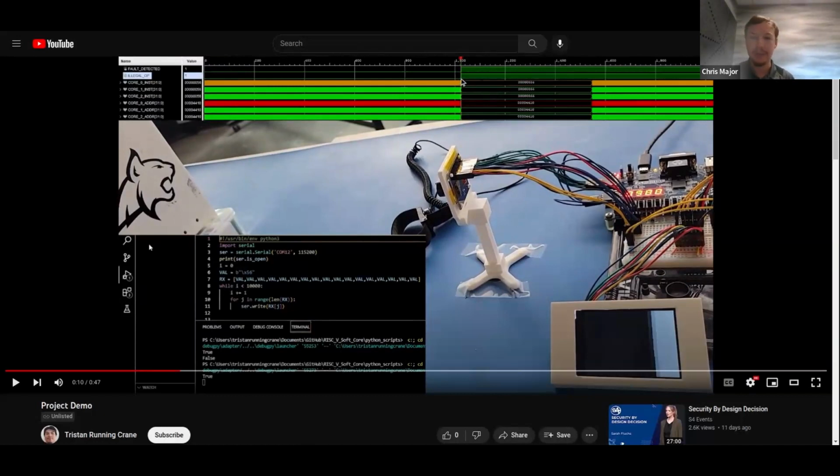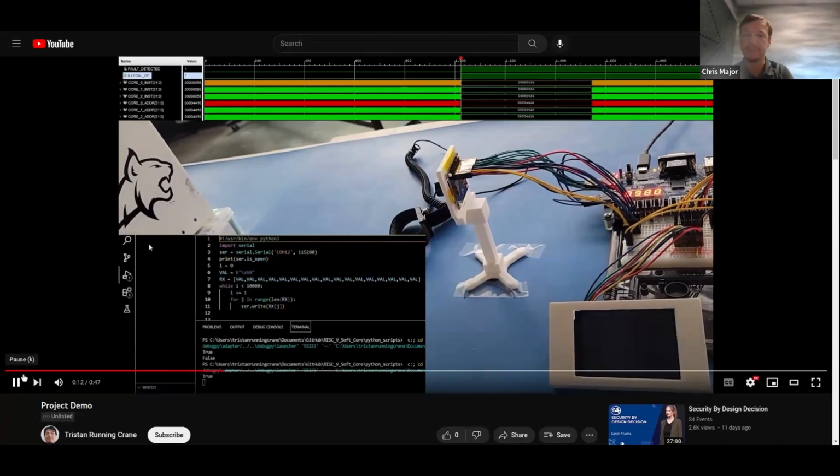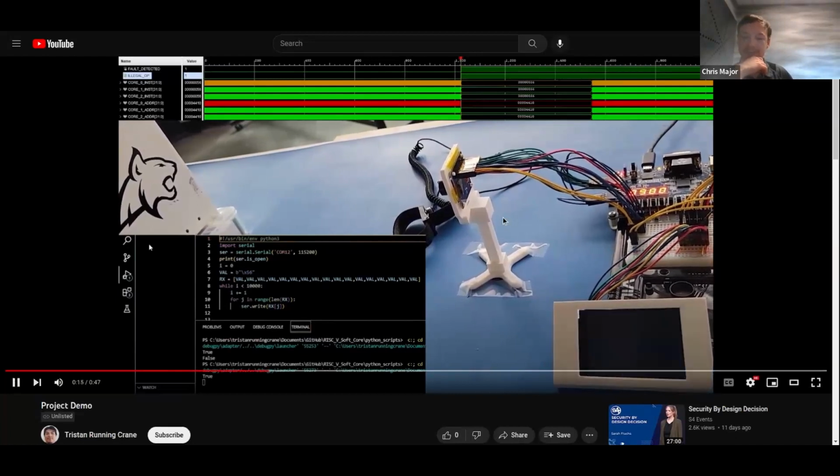But then the minute we hit this window here, which corresponds to right when the screen started acting up, we notice that we have illegal opcodes in the system. We know they're illegal because they're the same 4 opcodes across all 4 tiles, and the cores just don't know how to handle them, because these are foreign opcodes they can't understand. These flags go high, and now we force the processor to reset before it can actually try and run the malware. So as you can see, the attack has technically been performed here with the screen blinking, but you'll notice that it recovers in just a second.